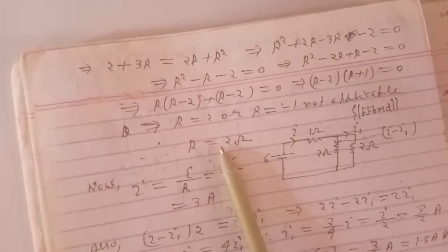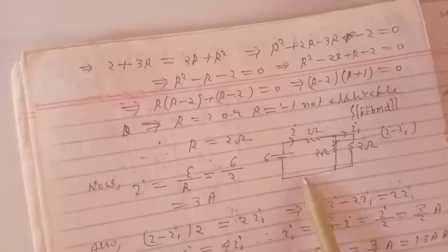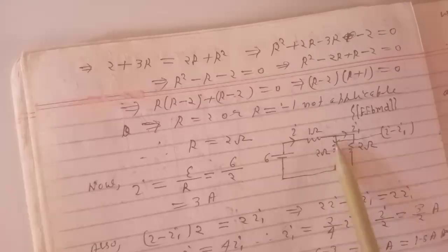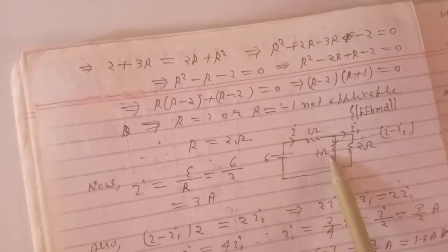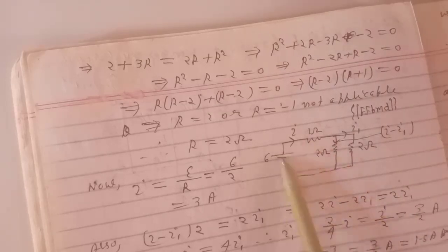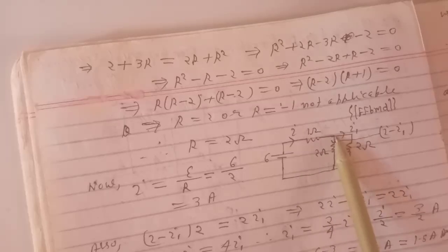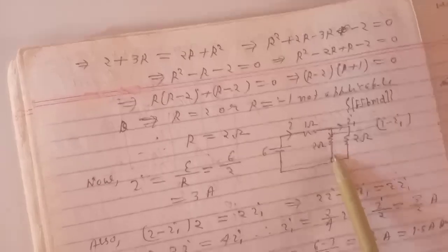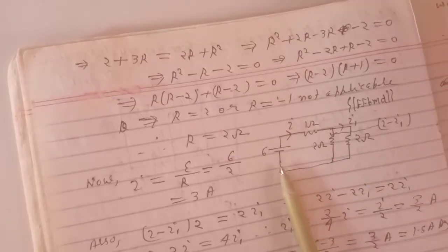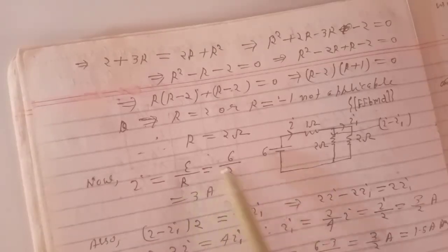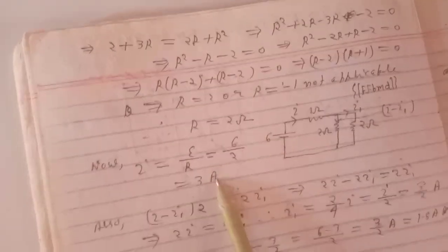So the new circuit diagram will be like this. This is 1 ohm, this is 2 ohm, and this is 2 ohm. And we have to find the current flowing through this 2 ohm. Now consider current I coming from the battery, and at this point in this direction goes I1, so in this it will be I minus I1. Now we can write I equal to E by R, because R is the equivalent resistance, and the value is given as 6 by 2, so 3 ampere. So I will be 3 ampere.